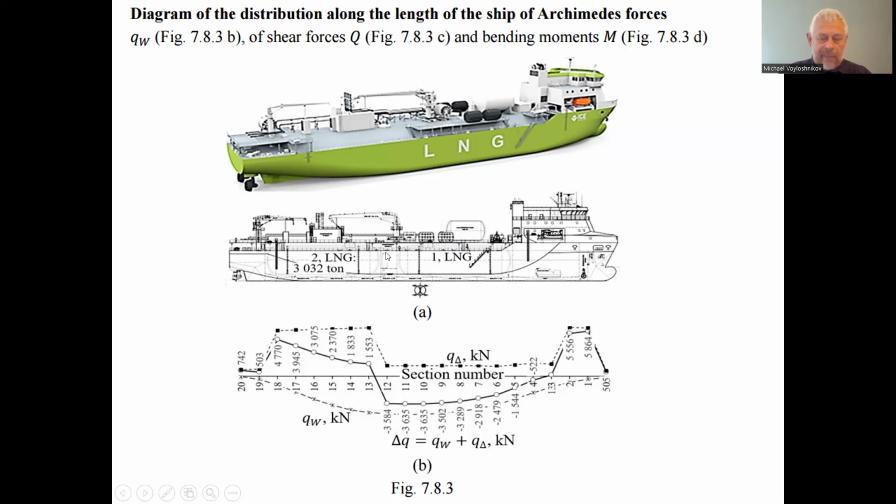So we will consider the loading state of the ship with the cargo in the aft capacity, a little bit more than 3,000 ton. And we consider the availability of the ship stocks, like the fuel, the variable stocks, maybe fresh water for the ship's consumption, and the ballast besides the stocks in the bow part, to keep the trim within appropriate limits, and to exclude the slamming of the ship when it moves in the water.